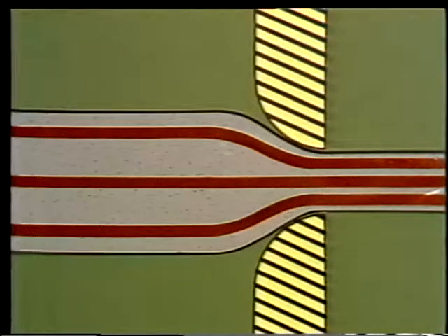Now, we talk of plasticity in metals in two ways. One is ductility. A ductile metal is a metal that can be stretched out to a thin shape without pulling apart. You take this copper wire, for example. Copper wire is formed by drawing the metal through a series of dies to produce fine strands from thicker rod. Ductility is deformation under tension.